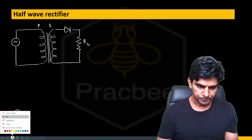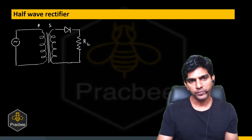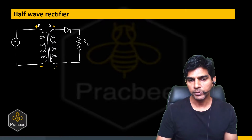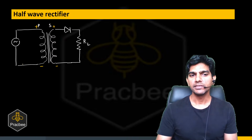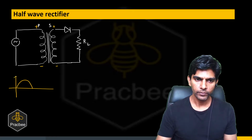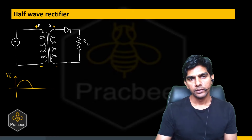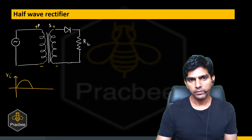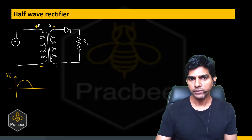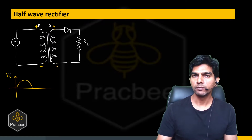Now if the top side of the primary winding is at high potential and bottom is at low potential, then in the secondary, the top will be at high and bottom will be low. So in the positive half cycle, this is our input voltage. The top side of the primary will be at high potential, bottom at low potential. Similarly, by mutual induction, the top side of the secondary will be at high potential and bottom will be at low potential.